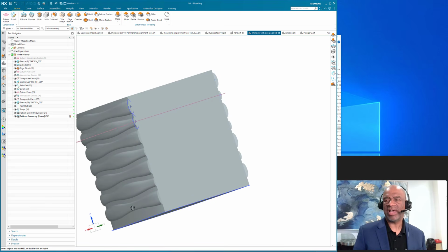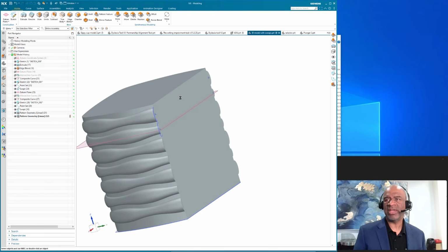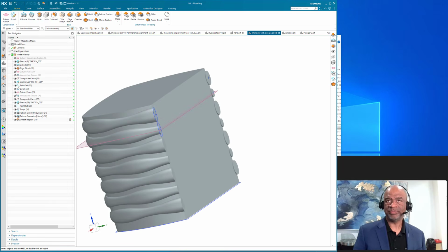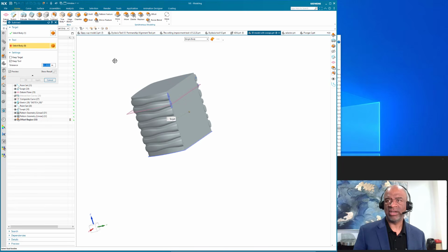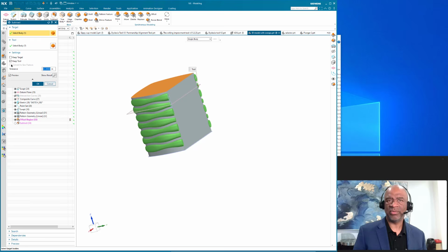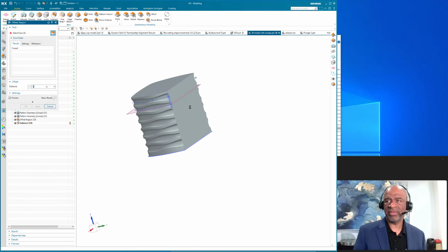I'm going to subtract all of these cutters, if you will, from the case, but before I do that, I'm going to take this little face right here and I'm going to offset it just a little bit, minus 0.25, and say OK. I'm going to go to the subtract tool, subtract, there's the target, and a bunch of tools, and say OK. And oops, when I did my subtract, there was the keep tool on, so I'll get rid of that, say OK. Then I'm going to do that offset. I'm going to put the offset back, 0.25.